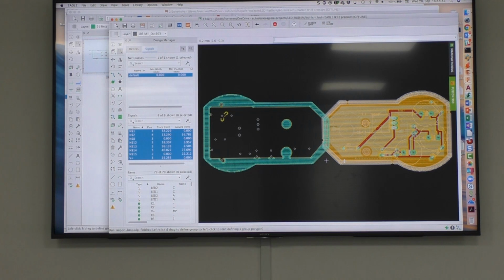a lot of objects, and if you want to use a logo in a board or something like this, then import it into the library as a package, and then bring it into the board, because then it's one object I can move around. Otherwise, I have to move all the lines. And if you need different sizes, okay, import 2, 3, 4, 5 times in different sizes, and then you can decide to use this or that.